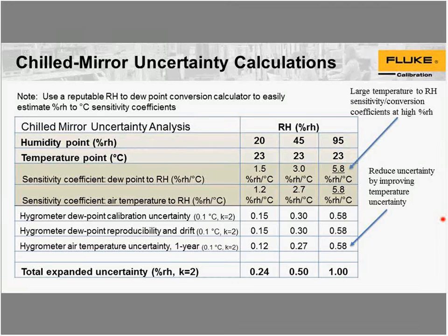How often do you calibrate the two-pressure chamber, and what is the cycle? We calibrate our two-pressure system every 6 months, partially because we are using them right up to the limits of their specs, and we want to keep a close eye on that. One of the things about a two-pressure chamber is that the calibration is done by calibrating pressure gauges.